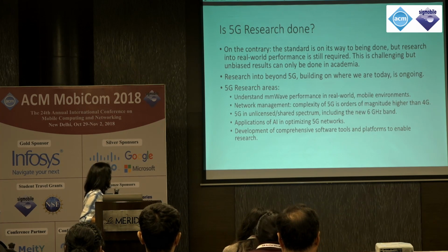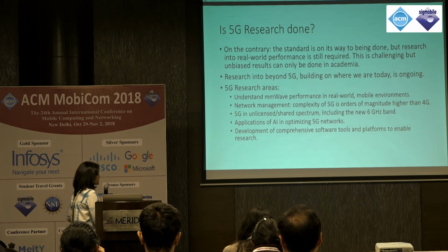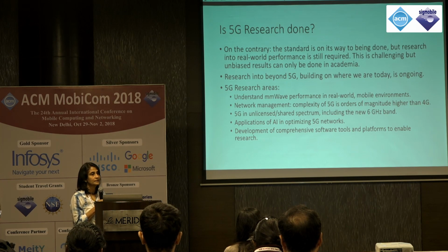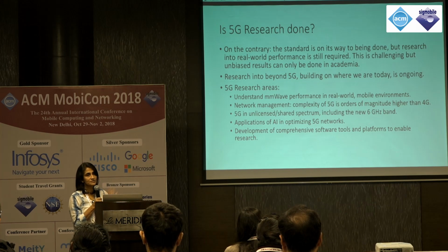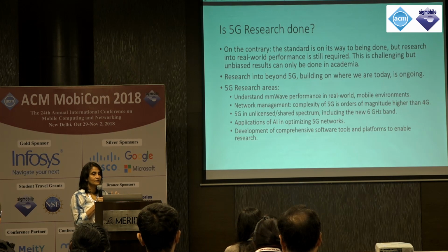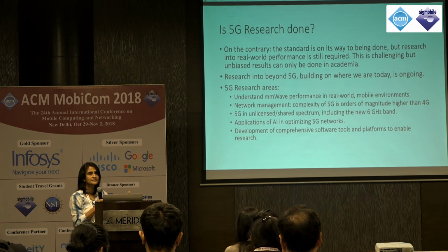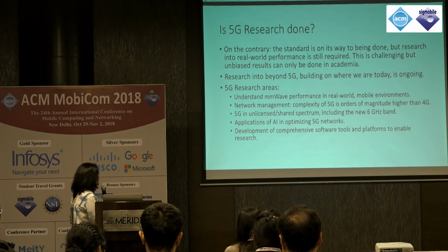Some of the 5G research areas, 5G today and beyond, are, for example, understanding millimeter wave performance in real-world mobile environments. Mobility is really, really tough for millimeter wave still. So there are a lot of ideas out there as to how you do handoffs, how you do base station deployments. Handoffs have always traditionally been done to one base station. Do we go back to the idea of being soft connected to multiple base stations at a time and you just switch beams? So there are a lot of new ideas that can be used in this space.